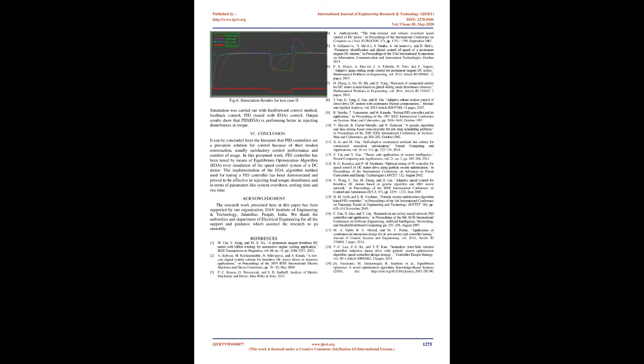6. Conclusion. It can be concluded from the literature that PID controllers are a prevalent solution for control because of their modest construction, usually satisfactory control performance and ease of usage. In this presented work, a PID controller has been tuned by means of the equilibrium optimization algorithm, EOA, over simulation of the speed control system of a DC motor. The implementation of the EOA method for tuning a PID controller has been demonstrated and proved to be effective in rejecting load torque disturbance and in terms of parameters like system overshoot, settling time and rise time.